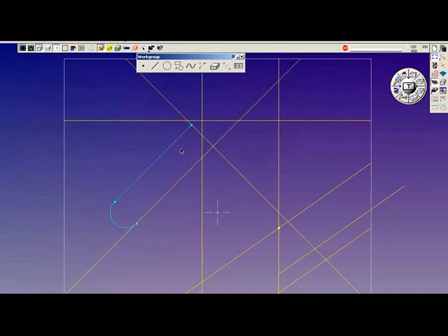All right, I'm going to connect this to this using the same technique. Pick one line, control click the intersecting line, click on the connect tile. That made the entire feature turn blue, and it is now connected. If you were to run a cutter on the outside, it would know to turn the corner at each intersection or connection. I can run it on the inside as a pocket, and this would be the boundary.